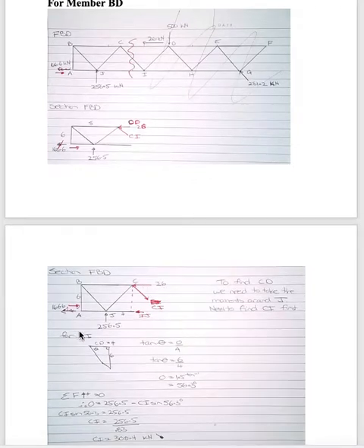Okay, so now I'm looking at this. And I'm wishing to actually find this one first. The reason I need to find this one is because I'm going to calculate the moments around J. Again, you think about it. If I calculate the moments around J, this is on J, this is on J, and anything else on this line is on J. So I can actually ignore all of those forces, and I'm back to my easy ones for my calculations.